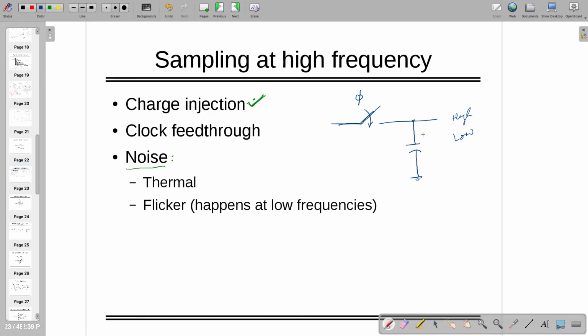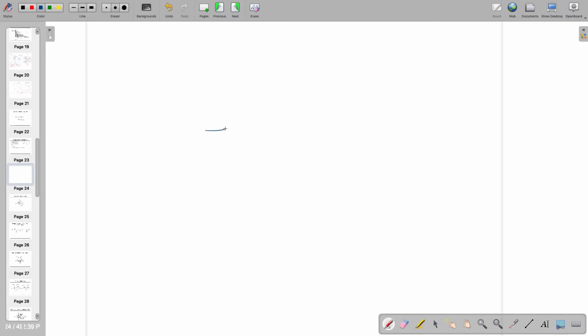If you want to rectify it, capacitance needs to be increased in this case, right? Generally these circuits, switched capacitors, are applicable at very high frequency, so you need to increase the capacitor. However, when you are doing this, we already learned that there is a function generator.